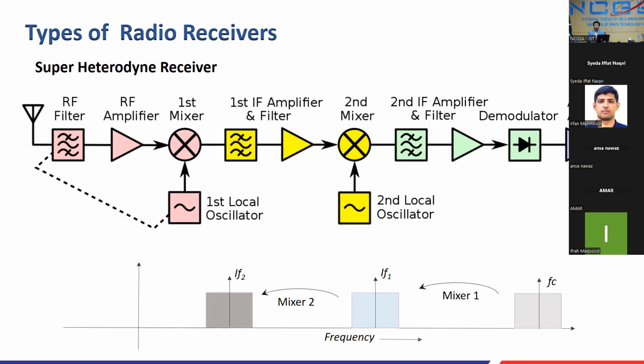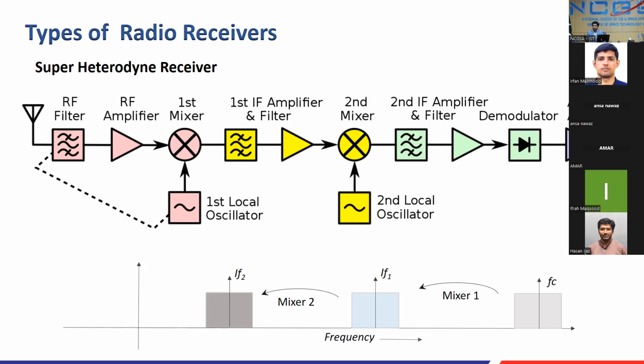For instance, I can share an example. Recently, we have been working on a system that has an IF frequency centered around 700 to 1200 megahertz. So we had to use an ADC at around 1300 MSPS with IQ sampling. The ADC was controlled by an FPGA. When the FPGA sent that data to the PC, the PC couldn't handle it, so from the 11th or 12th generation system, they moved to GPUs. The data was around 6 to 7 gigabits per second, so they needed PCI slots to handle that much data. I'm not talking about that part at present, but that is another aspect of collaboration with the digital team.